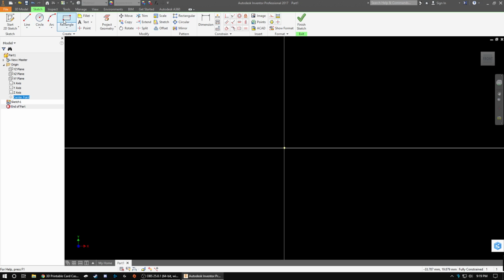These are the most common sketch geometry that's here. They have little pull downs to give you more options for the less common things. Line, you really only need line. You can use a spline if you need to do more complex shapes, but most of the time it's just going to be a line. Circle, ellipse, arc, different points of arc.